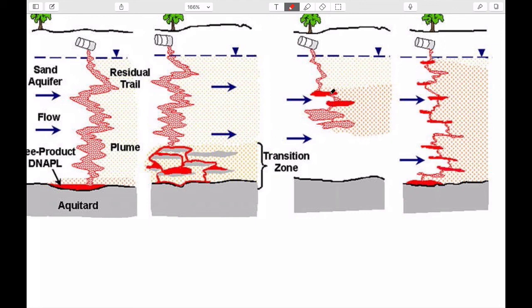and of course the next part is in contaminant hydrology, so we'll cease to be less interested in the portions which relate to the architecture of the free product, which is a really important part because it's basically the source for the contaminant stream that gets dissolved in water and ends up going downstream. We'll be interested more in the advective flow and what gets carried with that advective flow as a plume travels downstream. So we know that this behavior that we have here has a couple of important components.